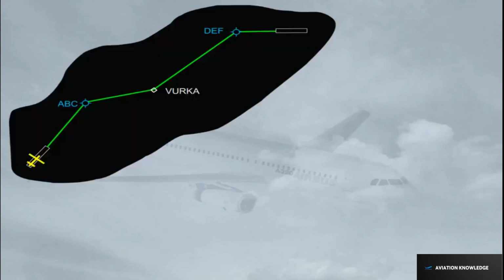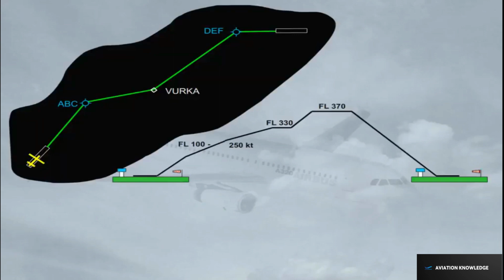For flight planning, the pilot inserts the following data into the FMGS via the MCDU. The lateral part of the flight plan. The vertical part of the flight plan, speed, time, altitude constraints, or step climb. In fact, two flight plans can be inserted in the FM. A primary one, used for the legs to be flown, and a secondary one, used to prepare an alternative departure or arrival or a diversion, which can be activated by the pilot whenever required.